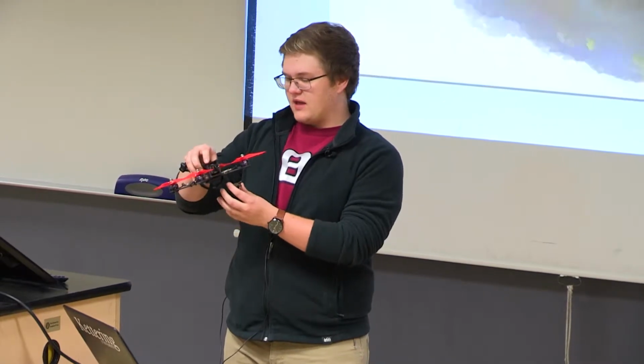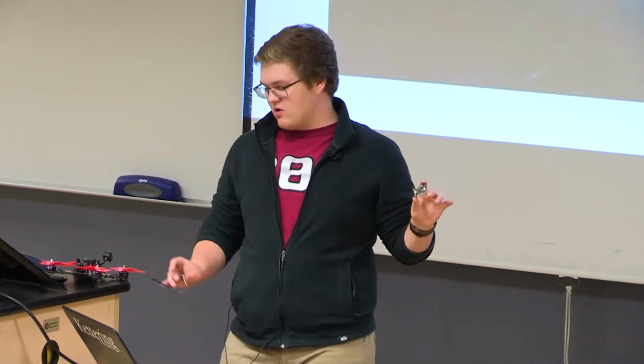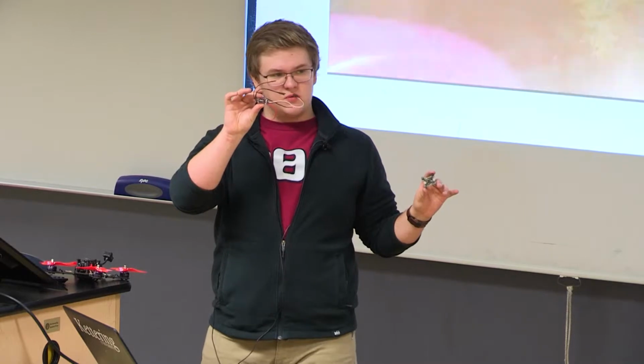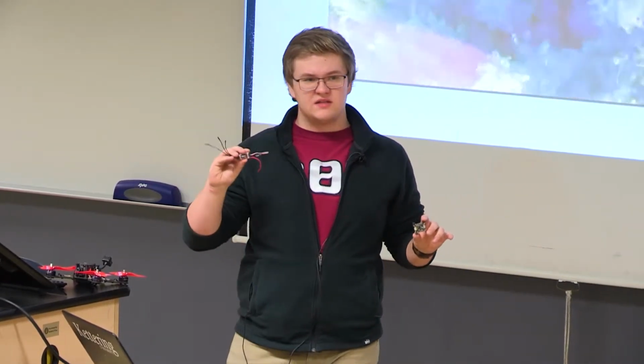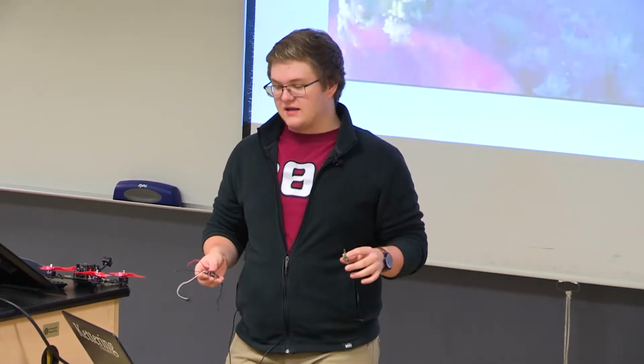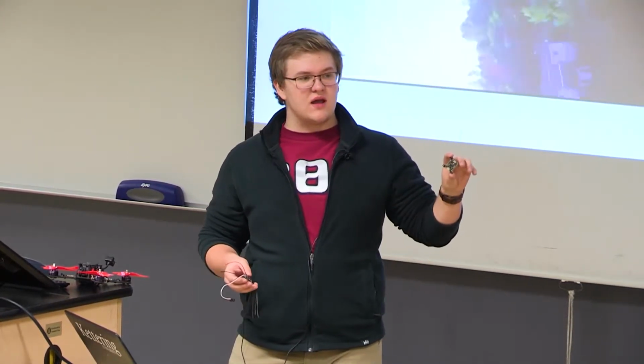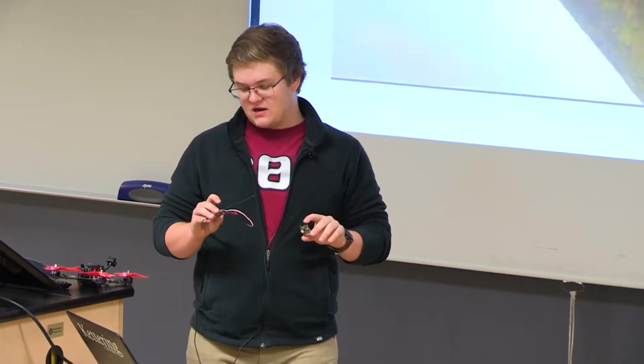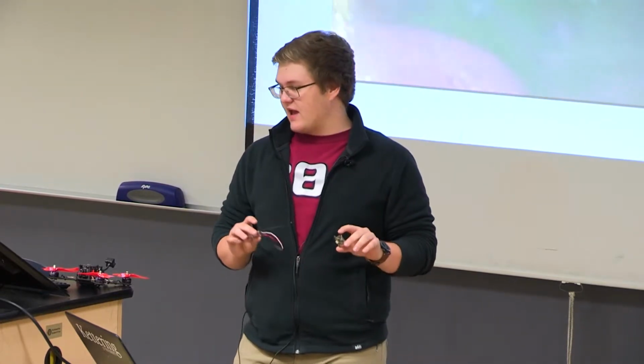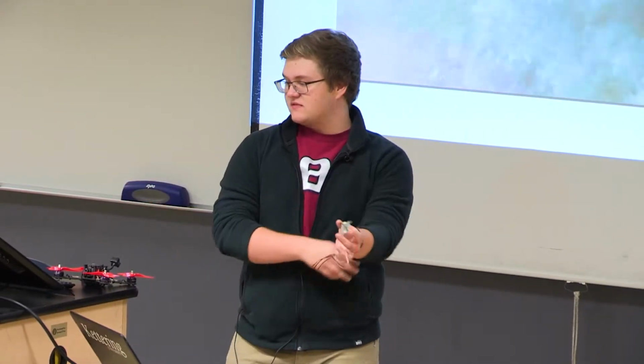It's interesting that when these first came out, they were pretty slow to respond. You couldn't fly acrobatics like what's going on behind you. Part of the reason is that between this control board and the motors is a speed controller. This is what actually controls the motors, and that introduces some latency and other things into the system. Nowadays, the algorithms running on this have been tuned to compensate for that and almost anticipate that lag, and you get a really responsive system.